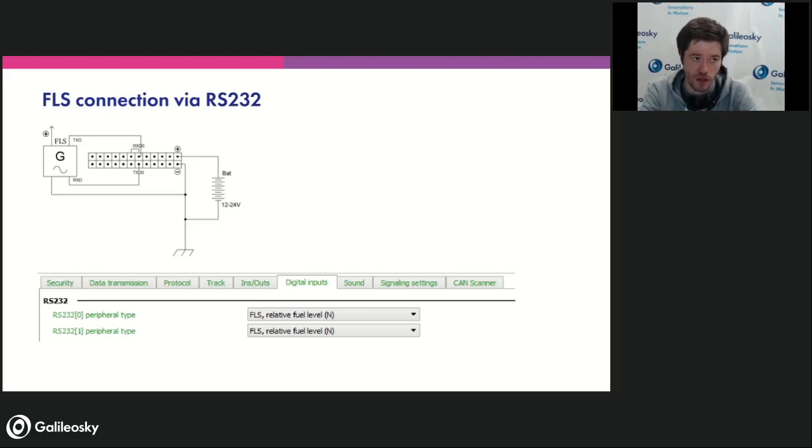So just to make sure, for both RS-232 and RS-485, we have integrated in the firmware only the LLS field level sensor protocol. In case your field level sensor uses a different protocol, the integration is possible, usually using the EasyLogic algorithm, which is a tool for broadening the functionality of the trackers. For example, we even have an example of such a script using the Modbus protocol. So if anyone doesn't have it yet and needs such a protocol example, we can send it afterwards, after the webinar.